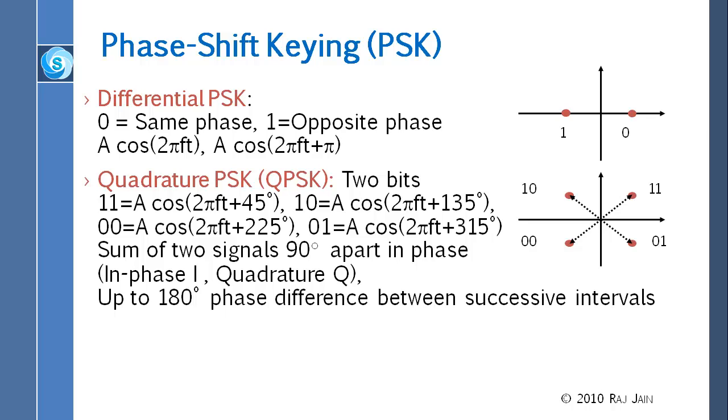Alright, with this coding, how many bits can we send? If it takes 1 second to find the phase, it will be 1 bit per second, because it will take 1 second to find the phase, whether it is 0 or 1. With this coding, if it takes 1 second to find the phase, how many bits can we send? 2 bits per second. Right? And both of these have the same frequency, same hertz, so the hertz is not even a question here. The question is how much.